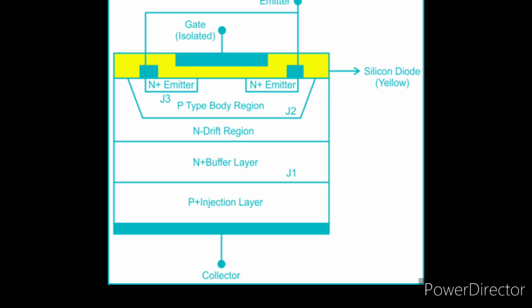It is lightly doped because when the device is off, it should block any high voltages at the emitter. We know that the width of the depletion region is inversely proportional to the square root of the doping concentration. Light doping means width of the depletion region is higher, right? Then the electric field spreads over a larger area because of the wider depletion region. So higher voltages can be blocked without reaching the breakdown. Whereas in heavy doping case, the width of the depletion region becomes smaller and the electric field is less, so